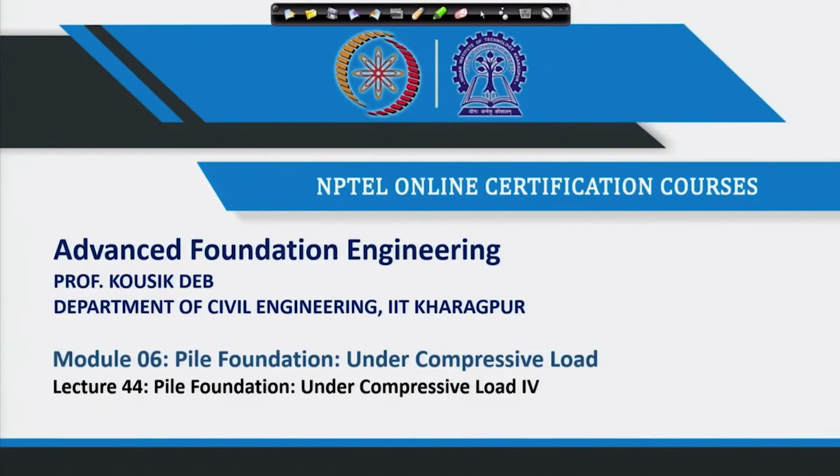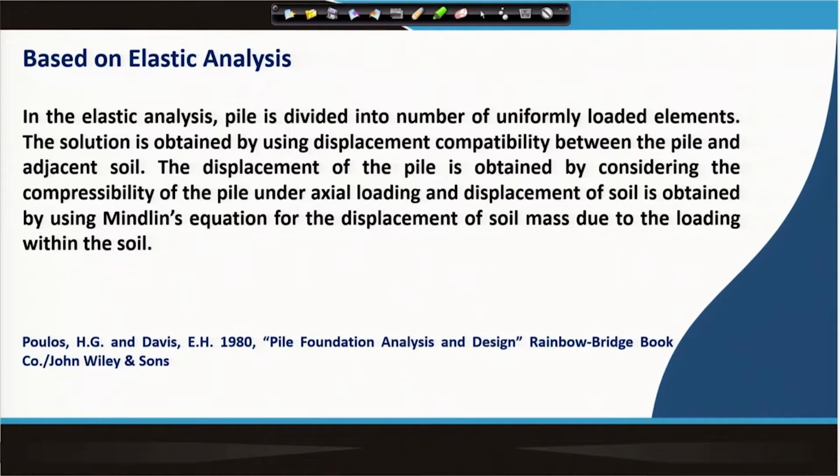Now, today I will discuss another approach, which is the elastic analysis. Based on elastic analysis also we can generate the load deformation curve theoretically. So, what is elastic analysis? In elastic analysis also the pile is divided into a number of uniformly loaded elements. The solution is obtained by using displacement compatibility between the pile and the adjacent soil. The displacement of the pile is obtained considering the compressibility of the pile under axial load, and the displacement of the soil is obtained by using the Mindlin equation for the displacement of a soil mass due to loading within the soil.